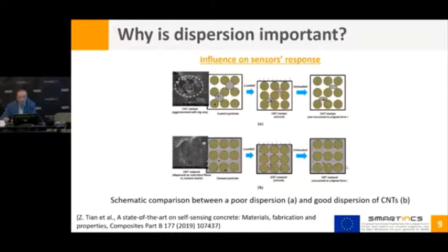And then we can say the same thing, considering that, as we said before, carbon nanotubes can behave as a piezoresistive material, so we can incorporate them, and also Gabriele has shown to us many times during his presentation, but we can use then the carbon nanotubes dispersed into the cementitious matrix as a strain or a stress sensor.